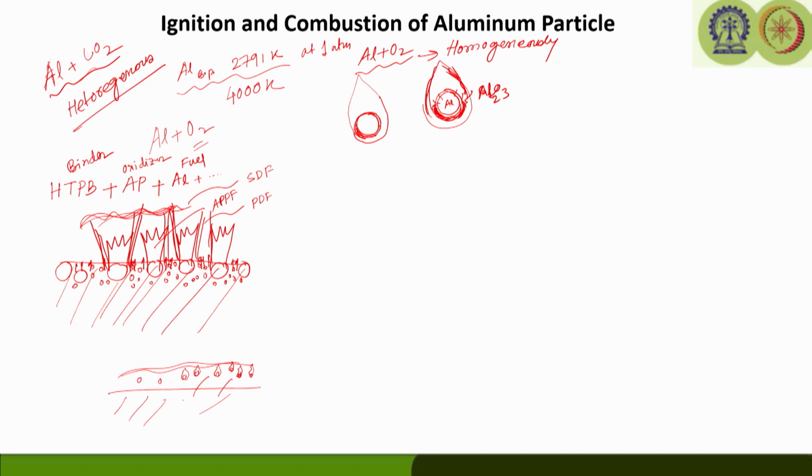Sometimes it has been observed that these particles and smoke are going to dampen the acoustic instabilities in a rocket motor. So, the amount of smoke produced during the combustion of aluminum is kind of important, because that is going to interact with the acoustic instability in the rocket motor, and it has been observed that somehow it is going to mitigate or dampen the acoustic instability.